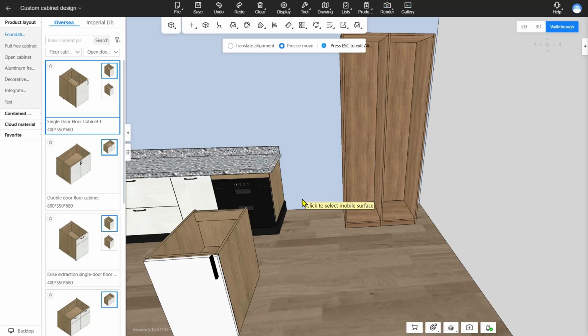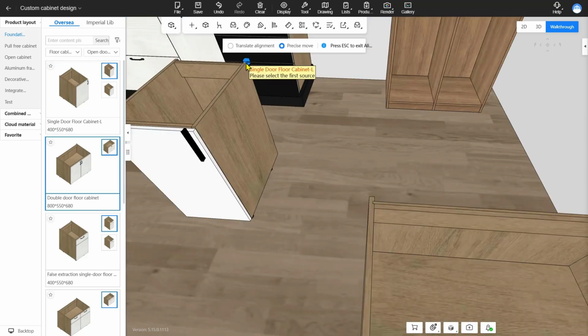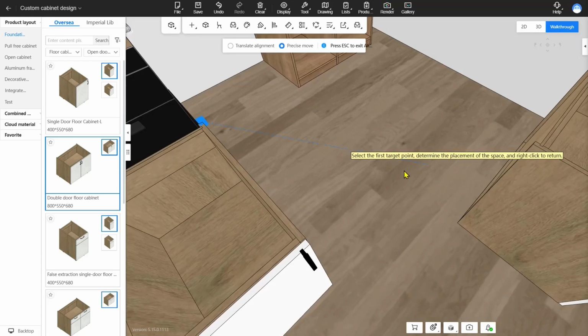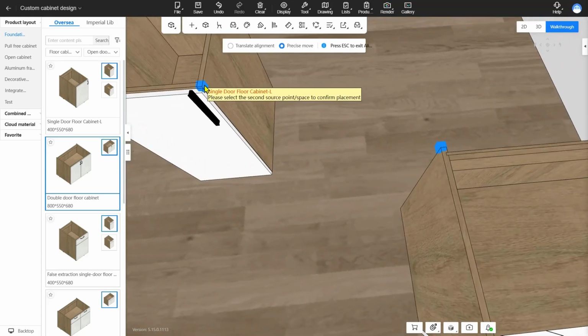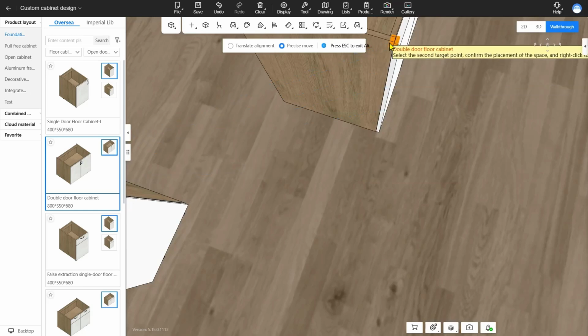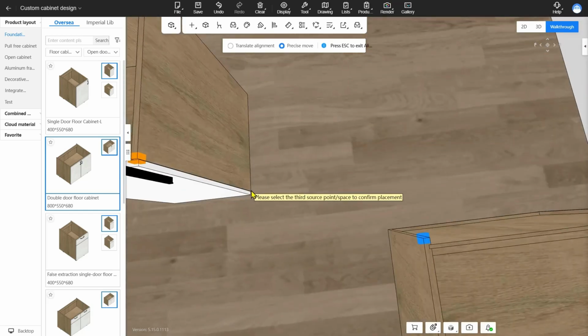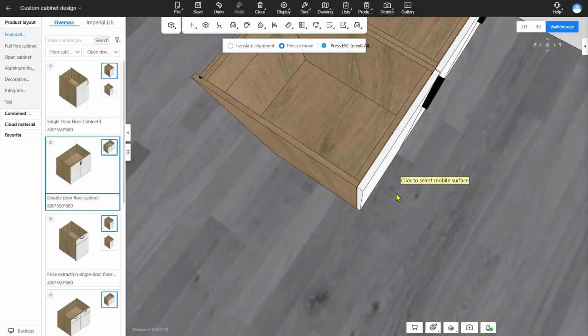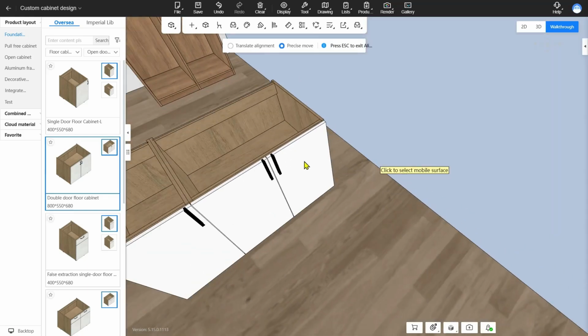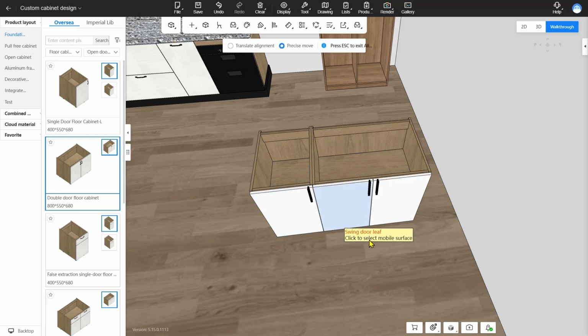However, for the point align, you need to select 3 points first. Second, and its target. Third, target for the third one. Then if you move to here. So this is the Align function. You can hit the escape key to escape from this function.